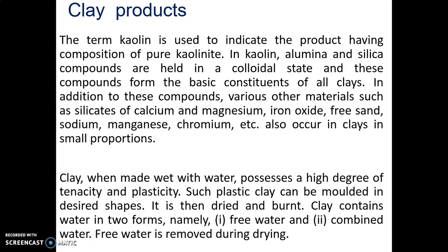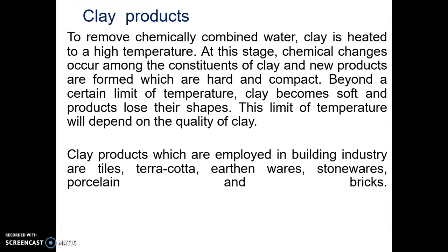Clay, when made wet with water, possesses high degree of tenacity and plasticity. Such plastic clay can be molded in desired shapes. It is then dried and burnt. Clay contains water in two forms, namely free water and combined water. Free water is removed during drying. The chemically combined water will be removed when the clay is heated to a high temperature. At this stage, chemical changes occur among the constituents of clay and new products are formed which are hard and compact. Beyond a certain limit of temperature, the clay becomes soft and the products lose their shapes. This limit of temperature will depend on quality of clay.